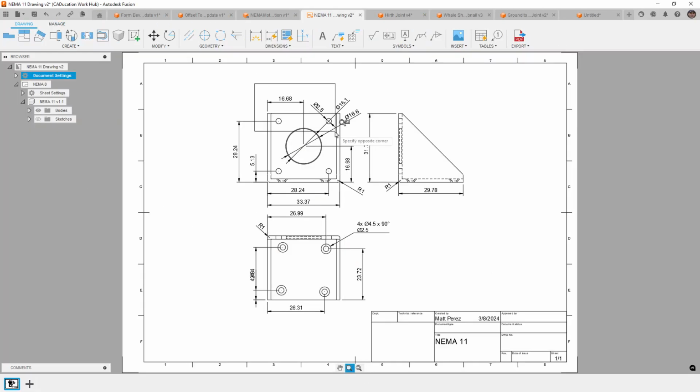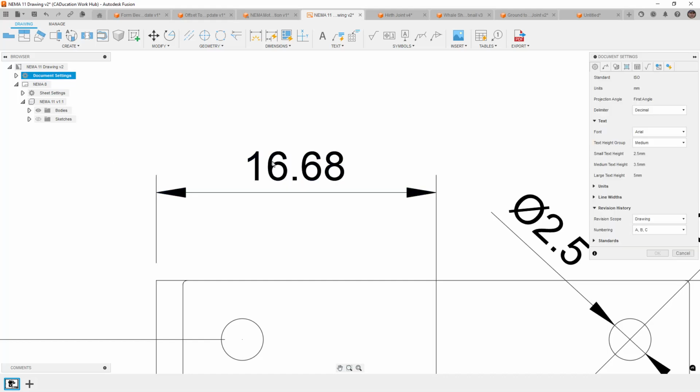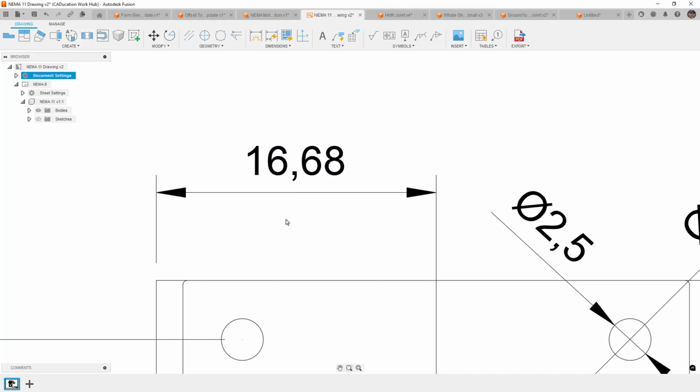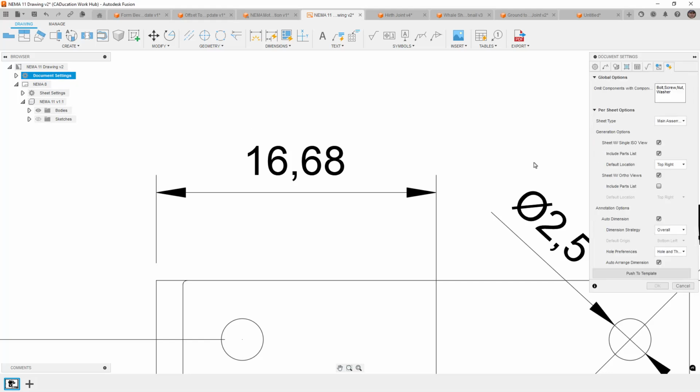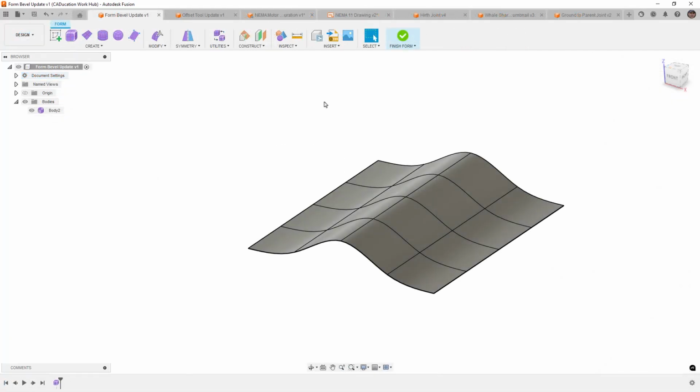So if you are creating toolpaths for CNC machining, then there are definitely a couple of great new updates in there. Things like using avoid and touch. In the past, you had to pick one or the other. Now there are settings for things like avoid and touch in the same toolpath. Big improvements, especially if you're doing complex shapes and you're using a lot of 3D or multi-axis toolpaths. So for this video, let's start with the design tools.